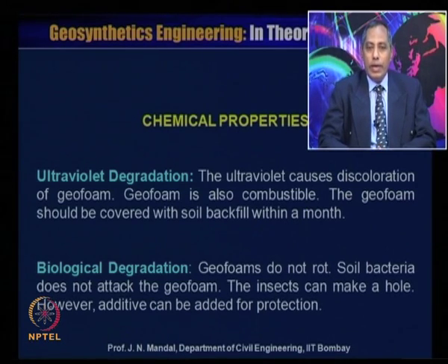Biological degradation. Geofoam does not rot. Soil bacteria do not attack the geofoam. Insects can make a hole. However, additives can be added for protection. In some projects in the USA, it has been observed that some ants made a hole for their nest.